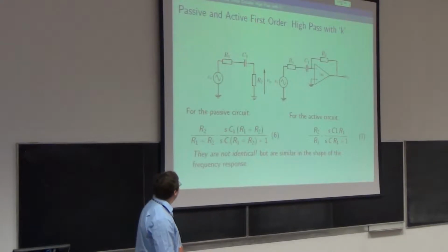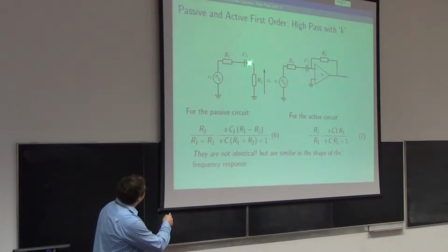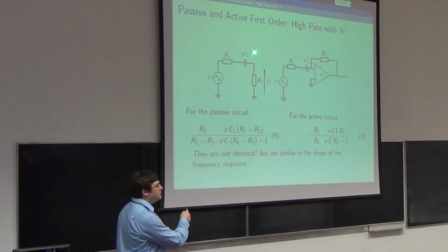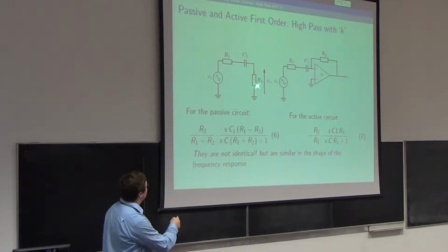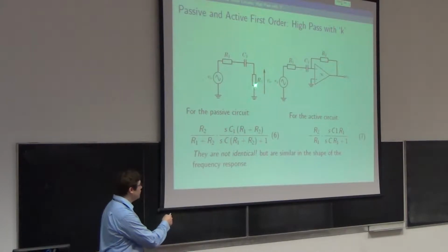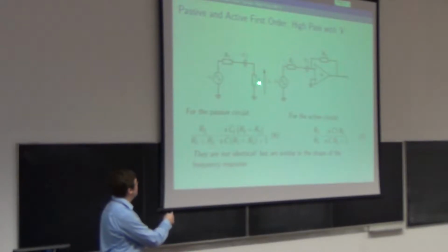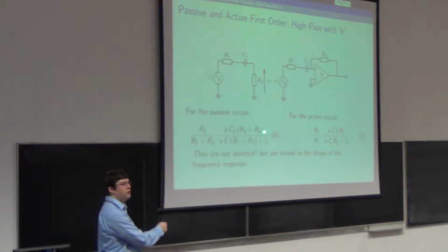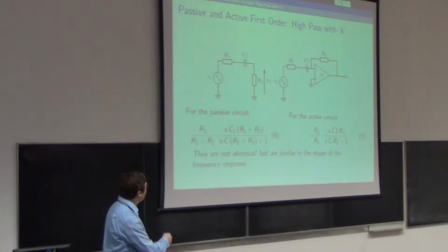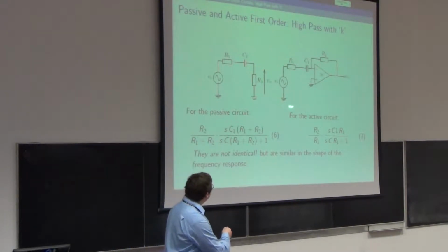I mean stuff. Right, so yeah, frequency increases, the impedance of C1 goes down, and we head into a situation where you have a potential divider of R1 and R2. So the best you can manage is R2 over R1 plus R2, which is your K, and all this stuff makes it worse at lower frequency. When I say worse, I mean more attenuation. Similar arguments for this one.